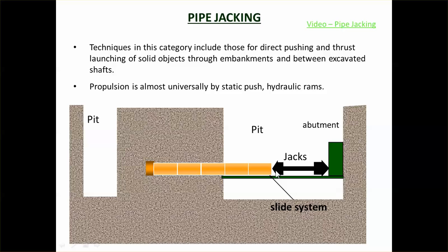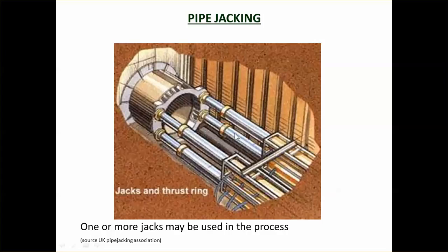In pipe jacking's purest form, it's actually just pushing it through, but nowadays you often have a motorized head on there, or you have people excavating at the head of it as well, so it's like a mini tunnel. There's a picture of the pipe jacking, those big pipe jacks. They push it through. When you want to feed another pipe, they withdraw, you drop the pipe in, then you just keep on pushing through.